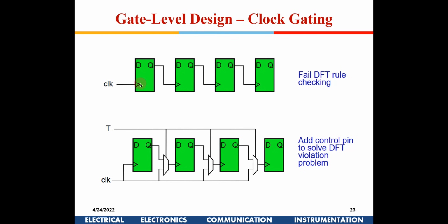For testing, it is important that we give a synchronous clock, give a test pattern, and see the output from each of the flip-flops. In this, if you give a clock like this, the fault gets propagated and you can't really fix where the fault is in this particular circuit.